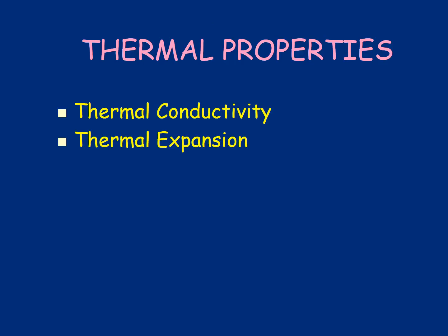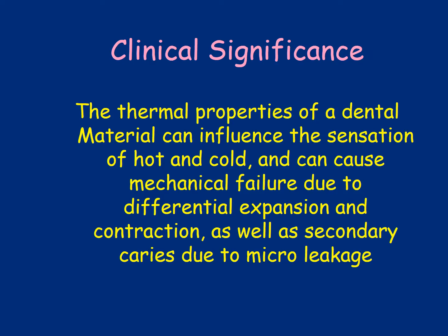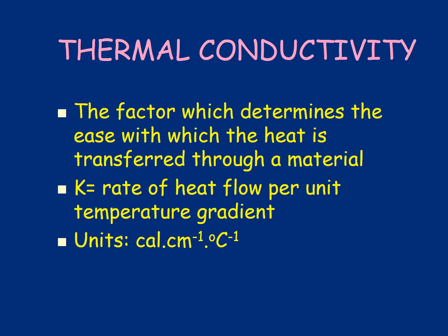The material that will conduct heat is a thermal conductor, and the material that will resist the conduction of heat is a thermal insulator. When you heat a material, there will be extra energy, and this will cause thermal expansion. Thermal conductivity determines the ease with which the heat is transferred through a material. It's represented by K, and it's the rate of heat flow per unit temperature gradient.